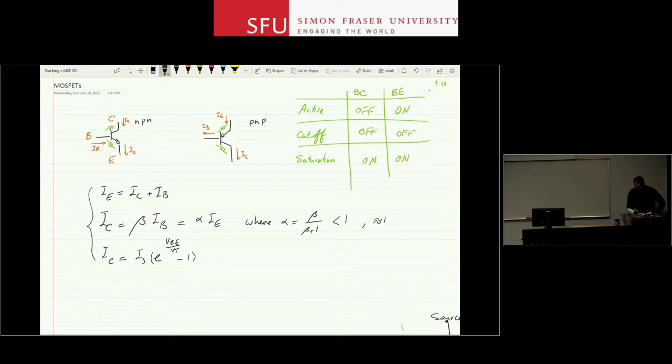And then we also saw that for a BJT, I'm going to draw the model for NPN. We saw at the end of that discussion that NPN and PNP are very, very similar. So if you learn one, you should be able to expand your information to the other one very easily. We use a hybrid pi model for the analysis of circuits with BJTs in them.